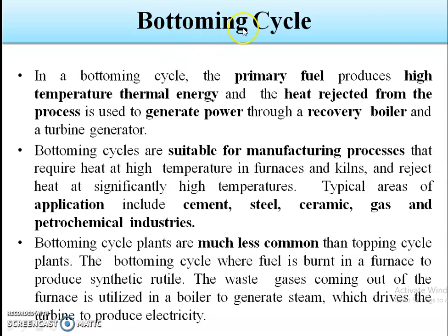In the next slide we discuss the very important bottoming cycle. In a bottoming cycle, the primary fuel produces high temperature thermal energy, and the heat rejected from the process is used to generate power through a recovery boiler and a turbine generator.